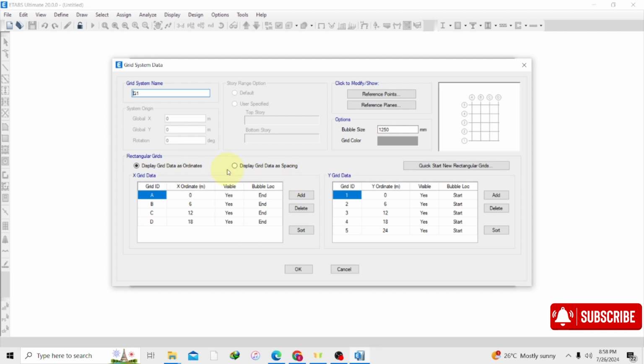So first of all, we are going to select display grid data as spacing. I've told you several times why we are going to use this, because ordinates is just a summation of the measurements. So at grid point A we have 0, at B we have 6, so just summation. So 6 plus 6 you have 12, then plus another 6 we have 18. It sometimes makes your reading of the measurements complex, so I prefer to use spacing. Spacing just displays the exact spacing between the grid lines. So we have 6 meters throughout.